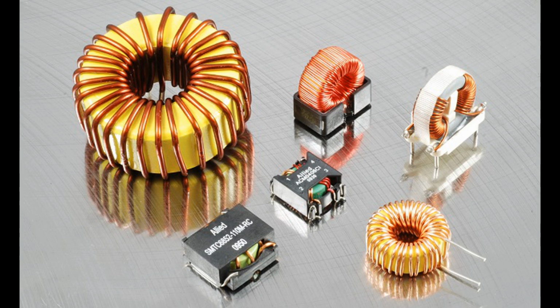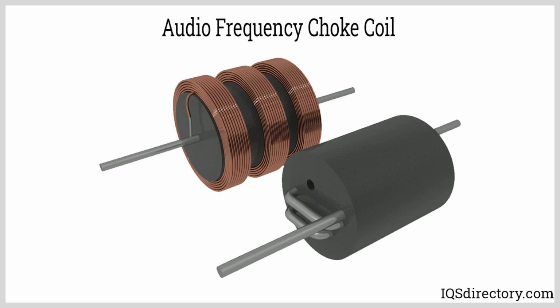Automatic choke. Automatic chokes use thermostatic control to automatically regulate the choke based on engine temperature. As the engine warms up, the choke automatically opens, reducing the fuel mixture. Found in many modern carbureted vehicles and small engines.